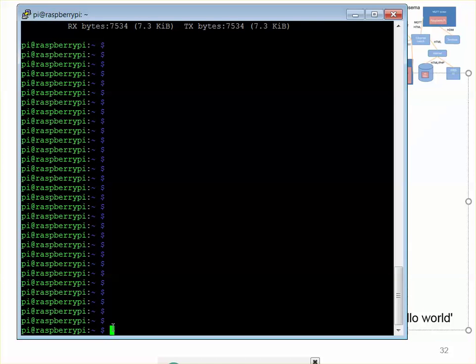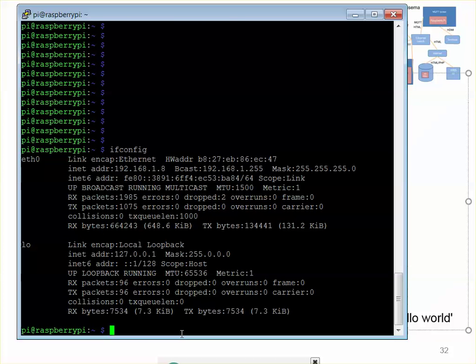And when you give that command, it tells you that this Raspberry's IP number is 192.168.1.8, and this number you have to put into your Arduino, because this defines the Mosquitto server's IP number, and they have to be in the same network so that the Arduino will reach this Mosquitto server.